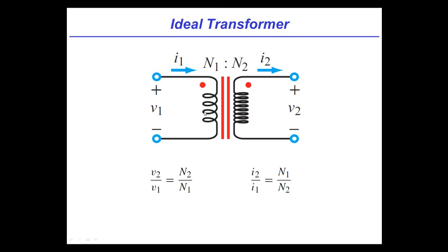Now, remember that assuming these are ideal inductors, there's no resistive loss in these. So one of the important consequences is that these are very, very efficient. They can be extremely efficient, but because there's essentially no place for power to be burnt off as heat, just as we have a step down in the driving voltage, there'll be a step up in the driving current. Oh, because P goes IV, right? Right. And the P in had better be the P out if you're not burning it away.